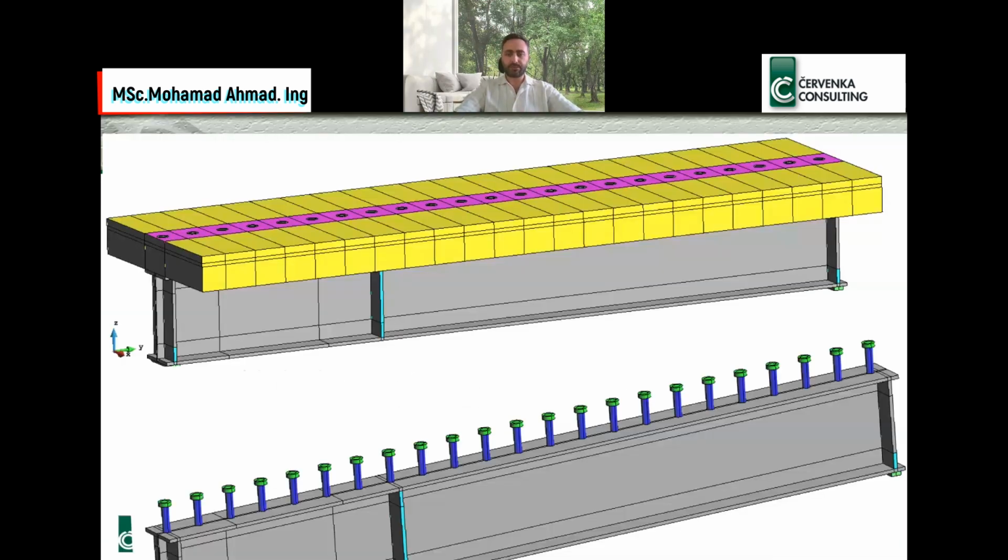Second example is about connecting a steel plate with a concrete slab on the top by shear connectors between them. As you can see in the photo on the bottom, the shear connectors are the volumes with blue colors. These shear connectors are welded with the steel and embedded inside the concrete in this area, the pink area.